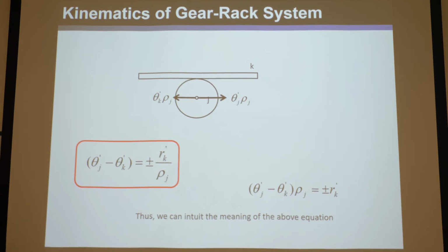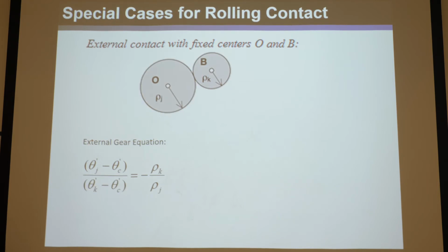Okay, so, all right, so let's do some thought experiments here. Let's say we're just going to have two gears that are pinned to the back plane. So that means basically the arm, the thing that connects these, you could think of, these guys are fixed to a link or a bar between point O and B, right? And if that's the thing held fixed, then that's basically just two gears stuck on a back plane.